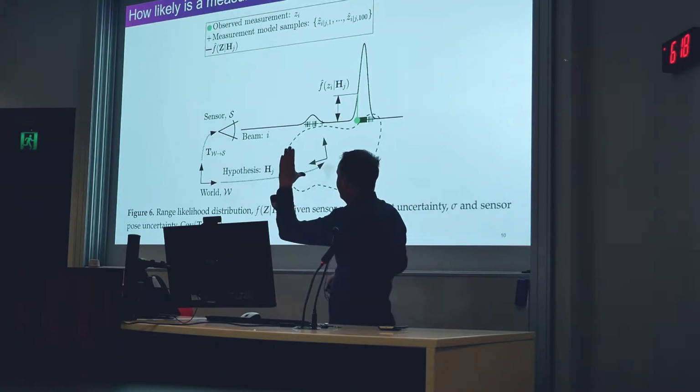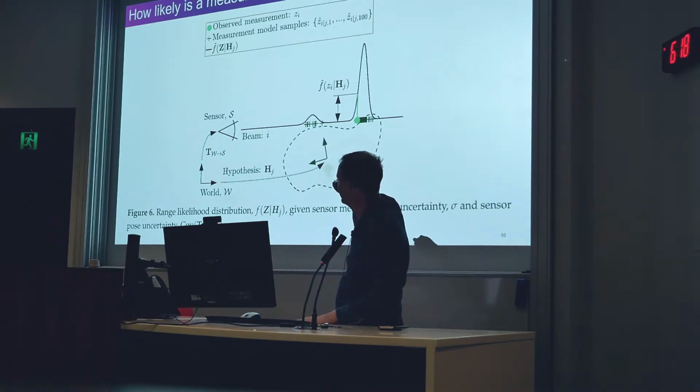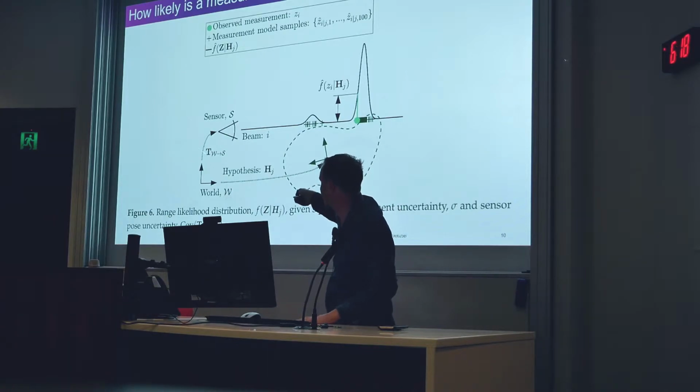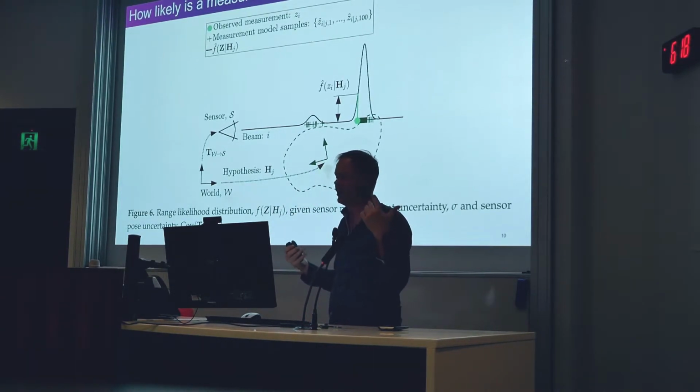Sometimes I might tilt the sensor down a little bit and it might actually start to intersect the nugget at the front. Other times it might intersect the nugget a little bit later or somewhere around here, right? So all of these little crosses, I think there's 100 of them. I've taken 100 samples of this uncertainty, repositioned it and raycast it again, and I've created this distribution here.